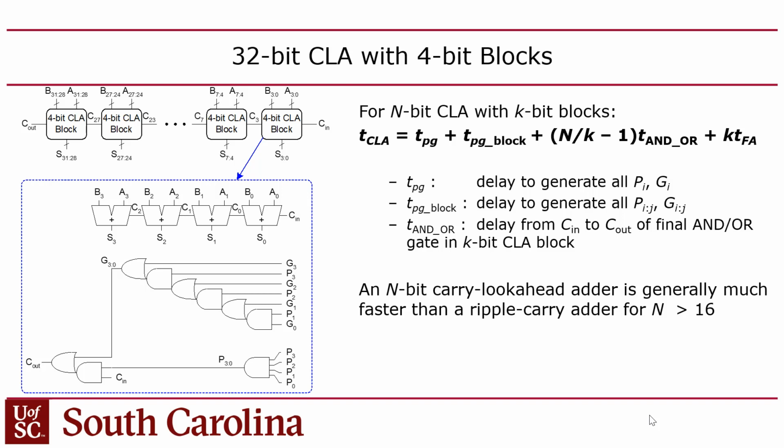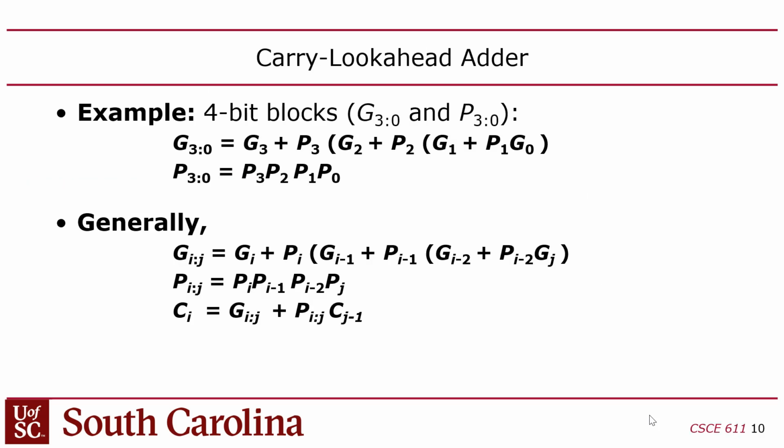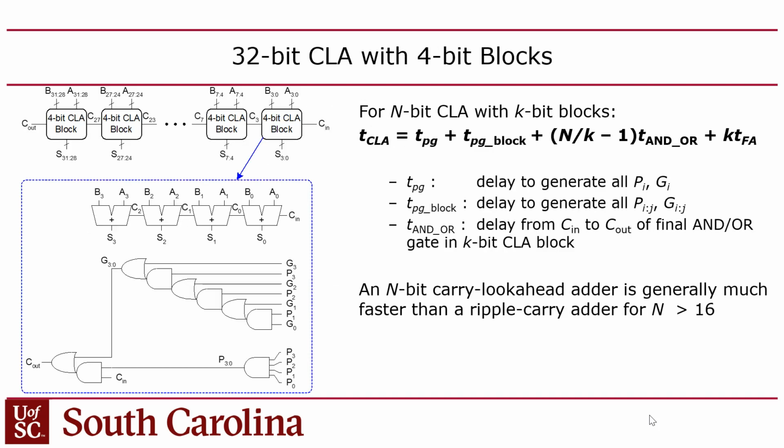So the propagation begins with that, and then once you have the individual bit P and G, you can calculate an additional layer of logic for generating the block level propagate and generates. And that would be just using this type of expression, right? Where you're taking the individual column PGs, and you're combining them to create block level PGs, right? Okay. Now, that's just a layer of logic that sits on top of the bit level PGs. So the signals come out of the inputs, they go through the full adders, you get bit level PGs, those flow into another block that gives you the block level PGs.